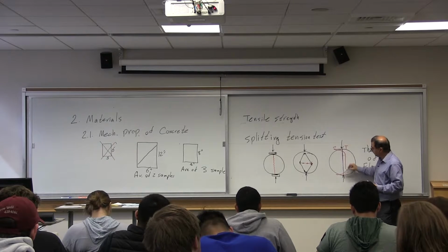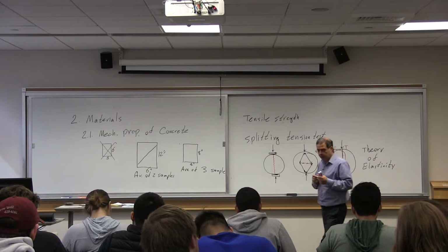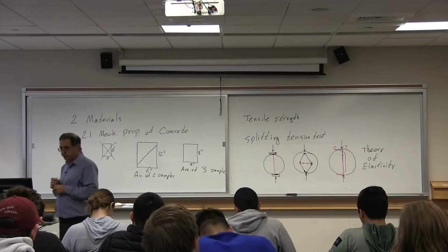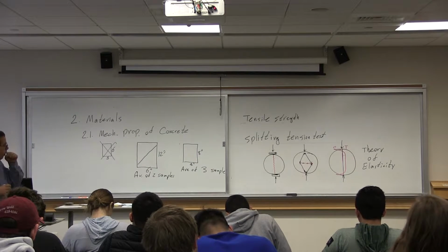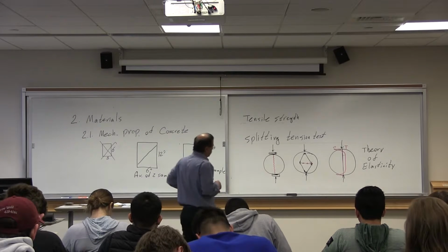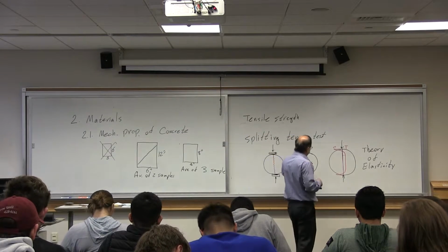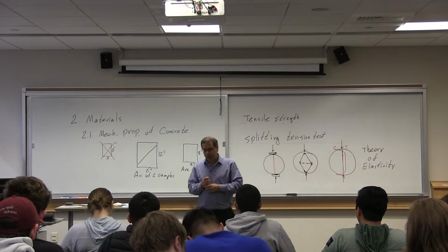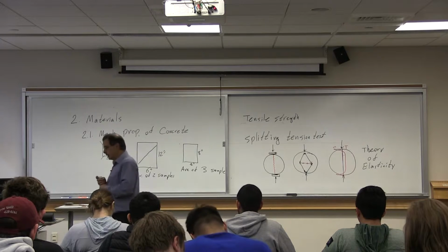Only at the very top and very bottom you have compression. So these are two ways of describing why this happens, but that is called, again, splitting tension test.